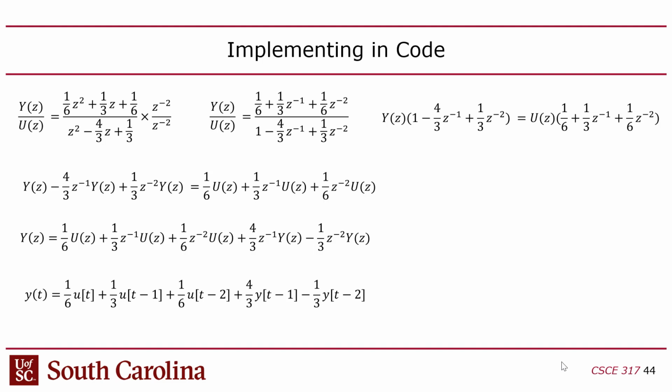The trick is if you can take your transfer function and get it into a form where all of the exponents of z are less than or equal to 0, then anytime you have a z with a negative exponent multiplied by a z domain variable, that translates in the time domain as the value of that signal one sample ago if it's -1, or 2 samples ago if it's -2, and so on. How cool is that? I think that's neat.